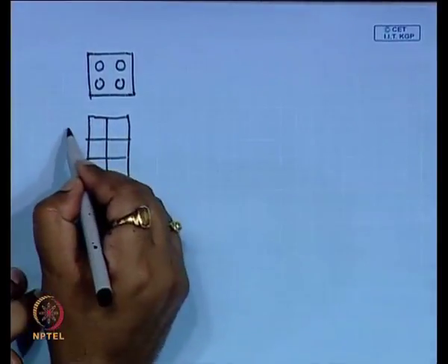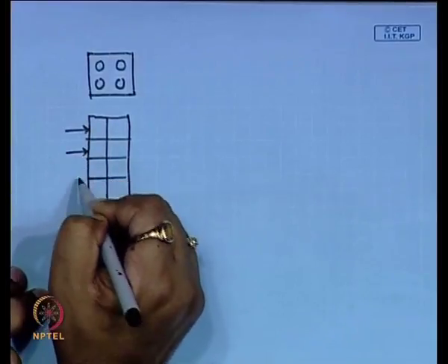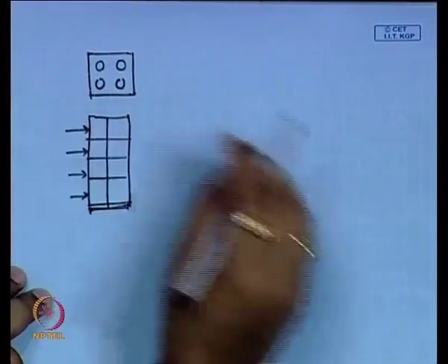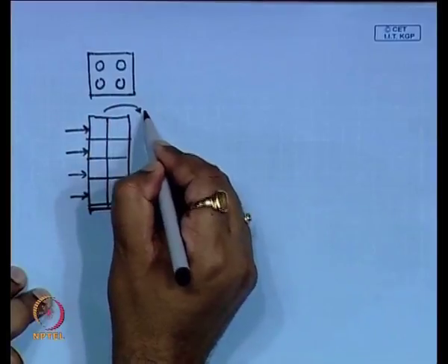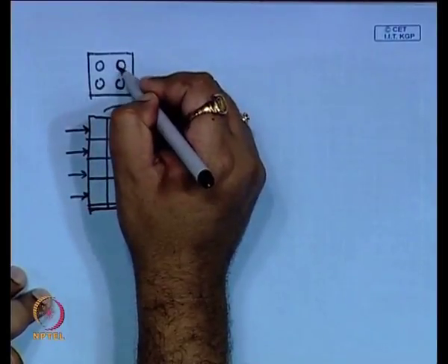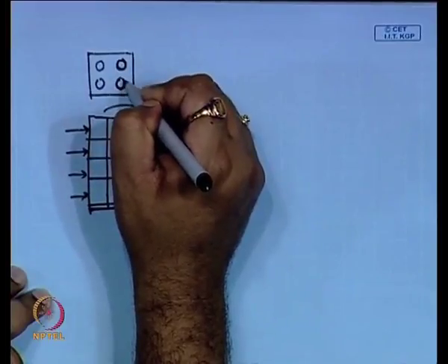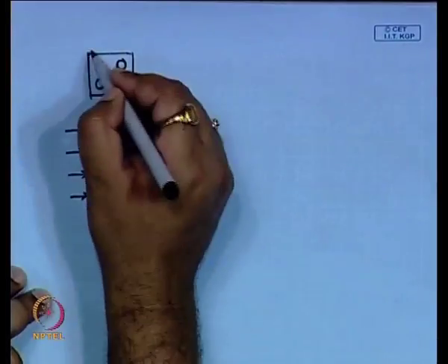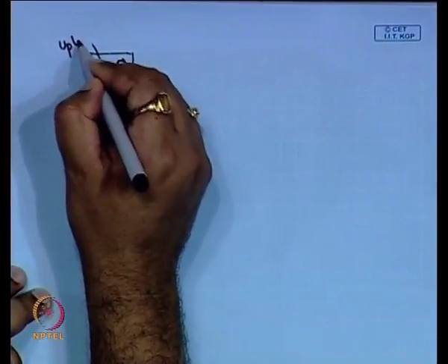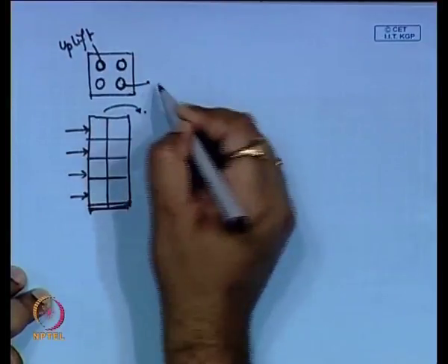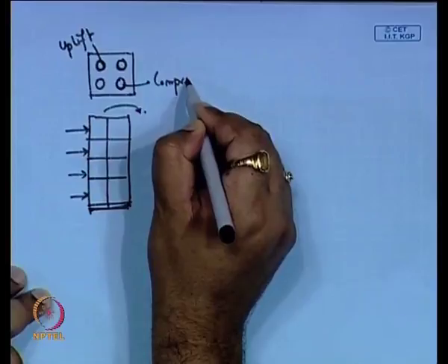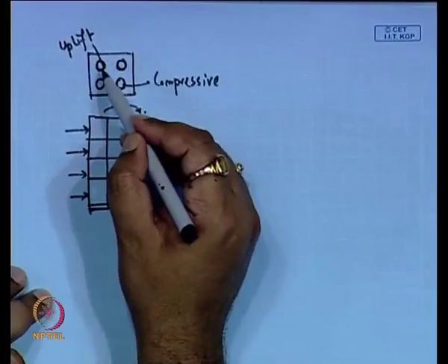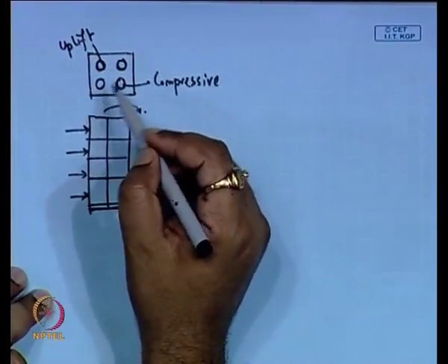Now, if the lateral load or the wind pressure is acting in the lateral direction, the total system will go in this side. So, here these piles will be subjected to compressive load, and these piles will be subjected to tension load, or the uplift load. Here we have to design these piles against this uplift load. This is the tension pile.